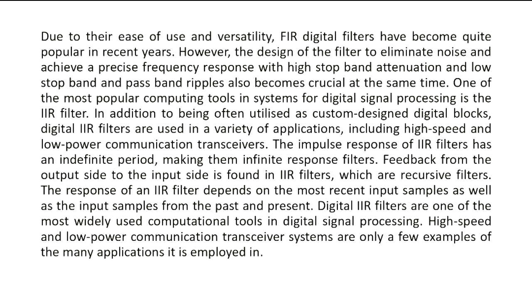The impulse response of IIR filters has an indefinite period, making them infinite response filters. Feedback from the output side to the input side is found in IIR filters, which are recursive filters. The response of an IIR filter depends on the most recent input samples as well as the input samples from the past and present. Digital IIR filters are one of the most widely used computational tools in digital signal processing. High-speed and low-power communication transceiver systems are only a few examples of the many applications it is employed in. So that's all. Thank you.